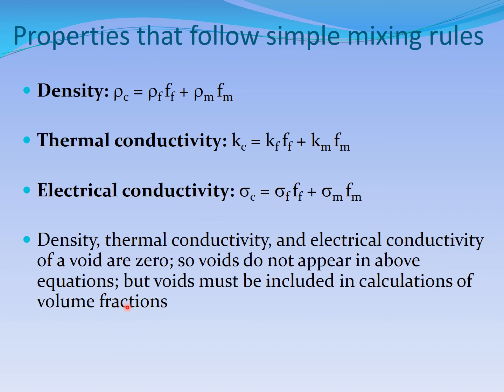But voids must be included in calculations of volume fractions. Volume fractions. Do you understand? Volume fraction, because voids are there. 1% voids are there, 2% voids are there. In the volume fraction calculation, voids will be there. In the density and conductivity calculations, they are not there.